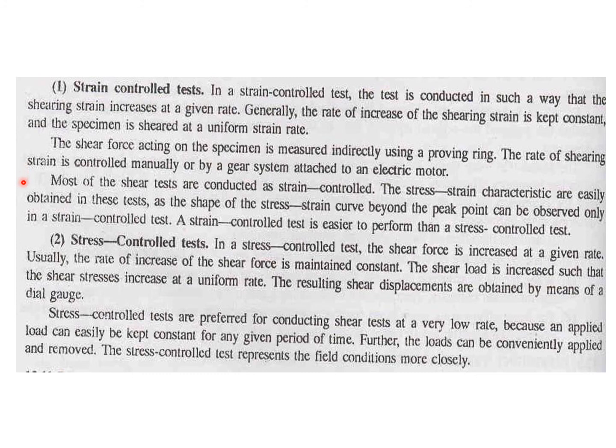Most of the shear tests are conducted as strain controlled. The stress-strain characteristics are easily obtained in these tests, as the shape of the stress-strain curve beyond the peak point can be observed only in a strain control test. A strain control test is easier to perform than a stress control test.